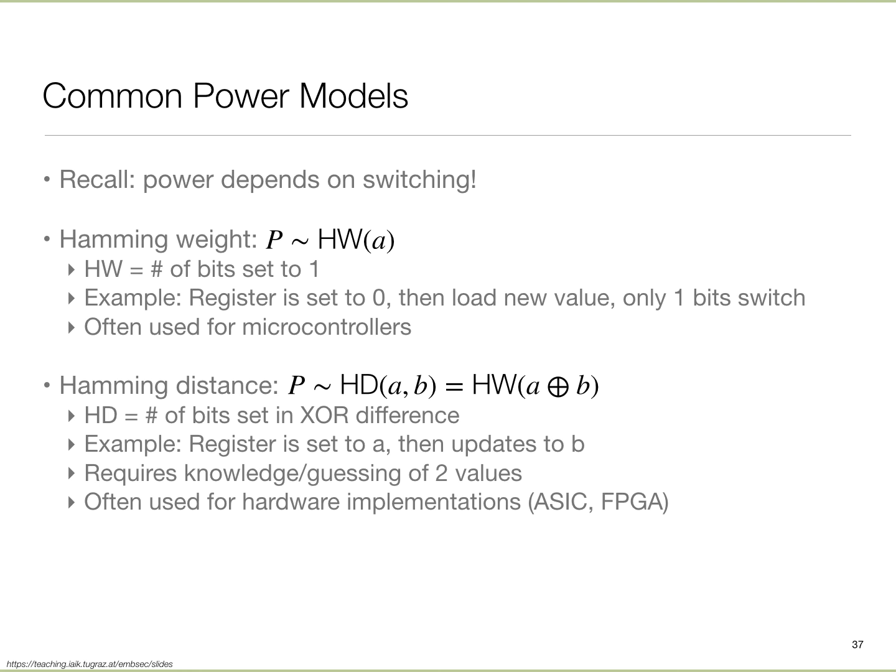For example, if it's a crypto operation, it operates on the keys, and depending upon whether the bit in the key was 0 or 1, the branching will differ. You could think that some model like this might work very well, because whether the bit was 0 or 1, it takes a different path. So my overall energy consumption over a time window would basically be a function of how many bits were 1. But other algorithms may require some deeper insight.